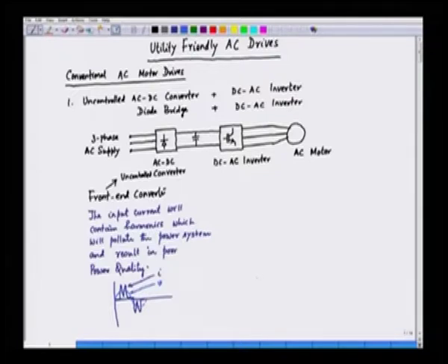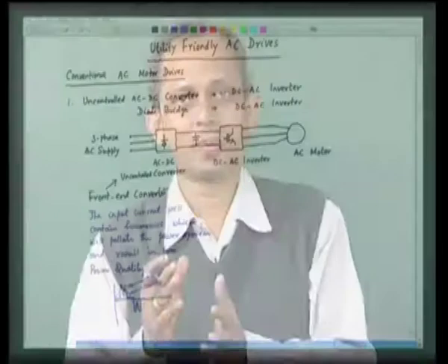Now, the current contains harmonics, and hence this drive, although we are able to control it through the inverter, will have a detrimental effect on the power system. So, this is not a utility friendly drive.